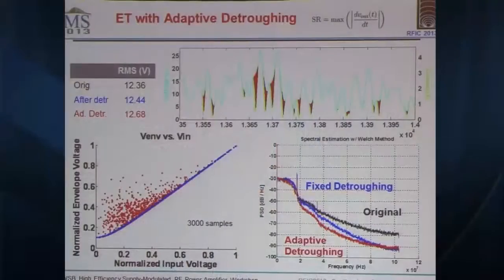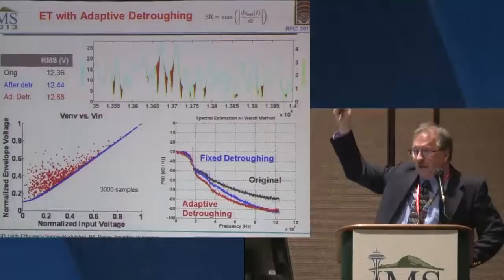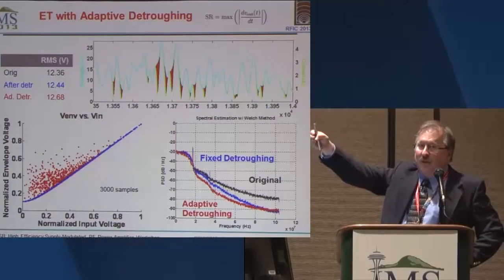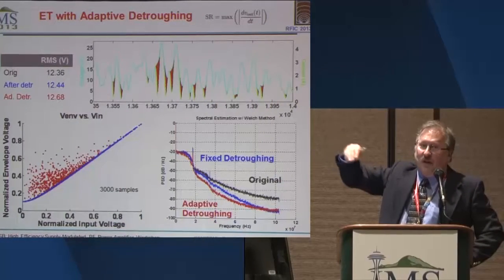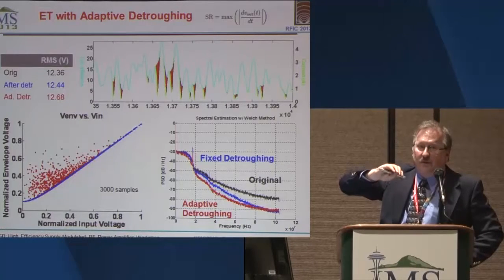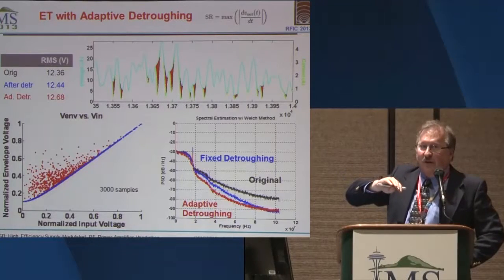But I still have to make up for that somehow and get linear behavior out of the output of the PA. And when I do that, we pretty much have determined that you don't want to be on the wrong side of the blue line here. If you get on this side of the blue line, essentially you'll need infinite RF input power to get to where you need to be for the output, and so you'll get extremely high peak to average ratios, and it just is not healthy for the RF chain.